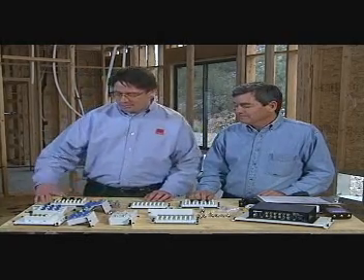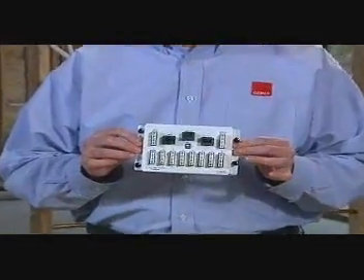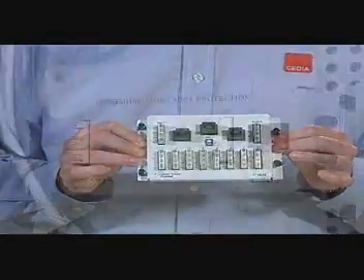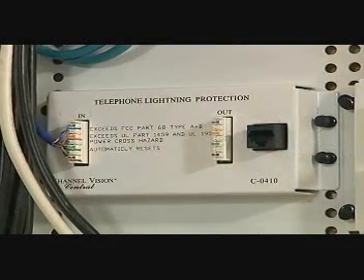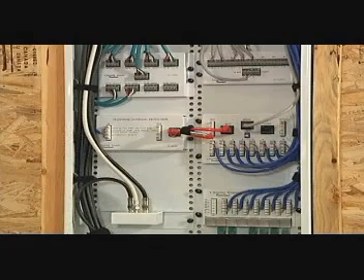In our project house, we need to support 24 voice outlets. So we'll be using 3 of these 110 style telecom distribution modules connected together. Secondary overvoltage protection on the incoming voice lines is a good idea, and most manufacturers provide this protection in some form. We'll use this surge protection module wired between the incoming voice lines and the distribution module.